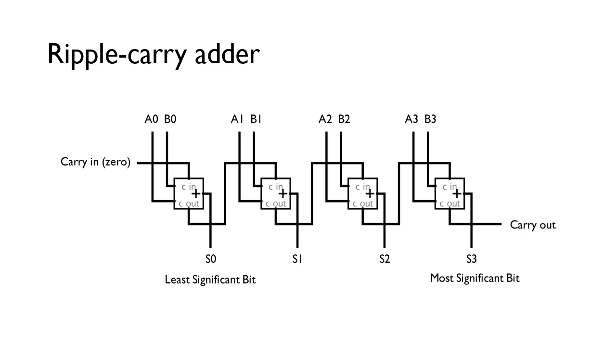So we'll look at a ripple carry adder here. We assume that the inputs, our A and B inputs and our carry in, are all applied at time 0. For the first full adder in the chain, it's going to take some time for this sum to be correct, and we've got to wait until this carry out is correct so it can be fed into the next one.